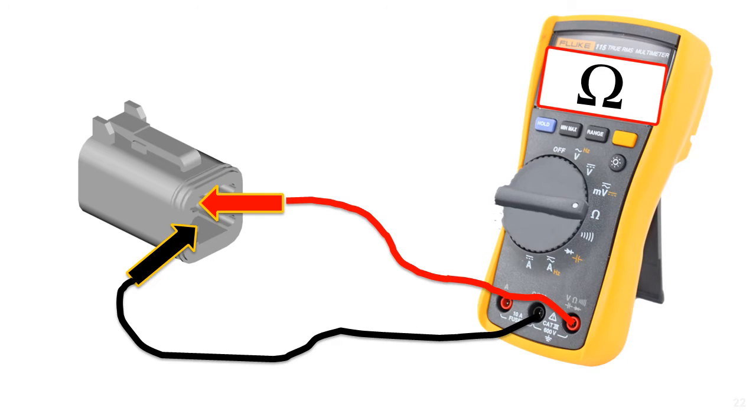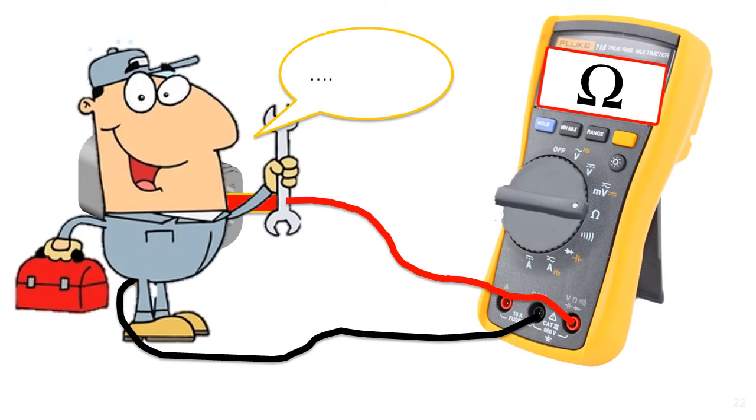To check the CAN network, turn off the unit and wait for the electrical system to power off. Measure the resistance between the CAN wires at the diagnostic connector. You should read between 50 and 70 ohms. If you're performing this test on a Spider, remove the main relay.